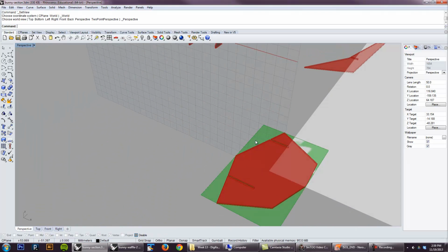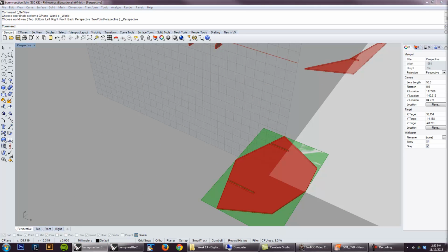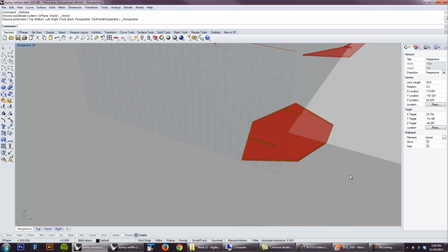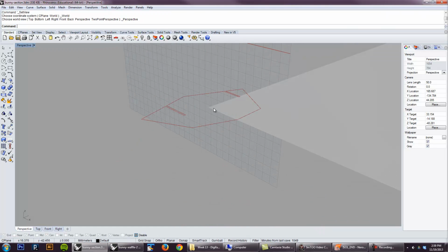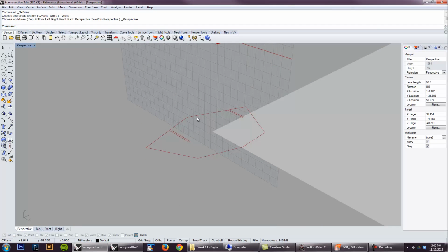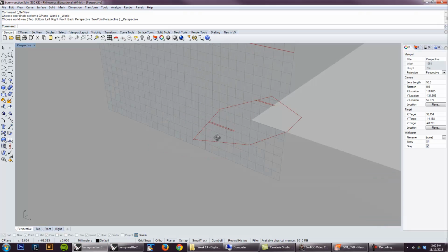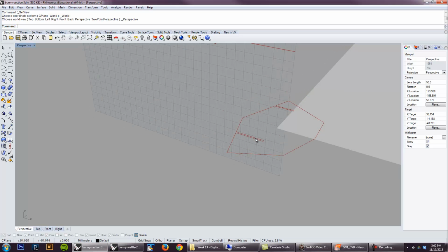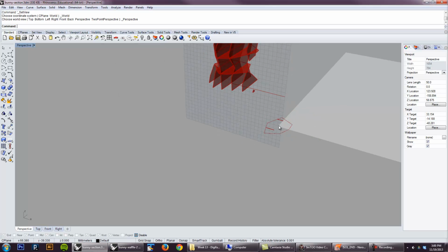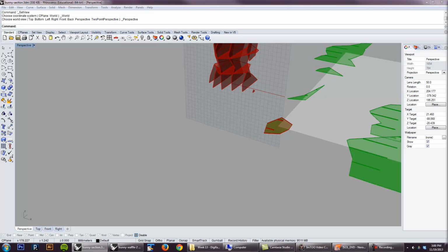And then once we take the intersection of those two objects, you'll basically get that flat curve. So just take a plane and essentially use it to do a Boolean intersection. Okay, and then this will be nice and bakeable. You can put a label on it, and then that'll be on your cut sheet. So let's go through that technique. I'm just going to focus on the one object, not all these objects, but the technique will certainly apply.